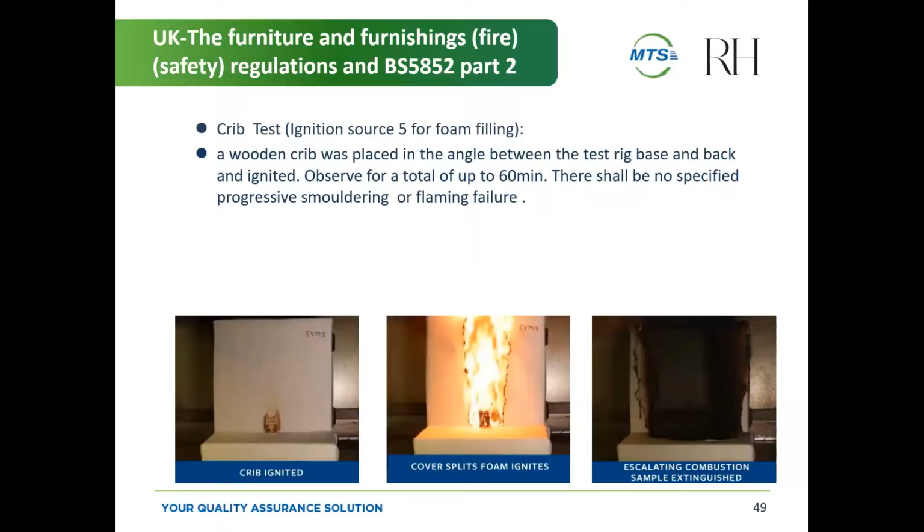This is the crib test. There's a small wooden crib, if you can see on the first picture to your left. In the middle of the crib is lit, and they observe it for up to 60 minutes. There should be no progressive smoldering or flame. And you can see what happens in a failed item.